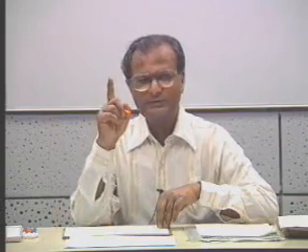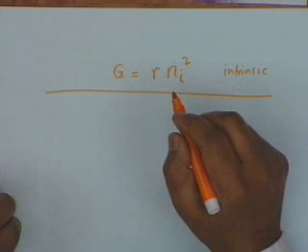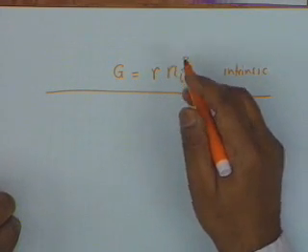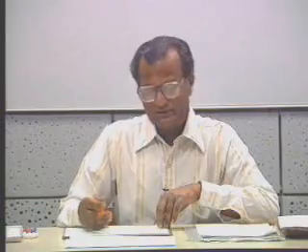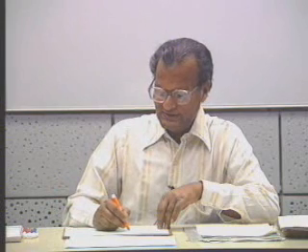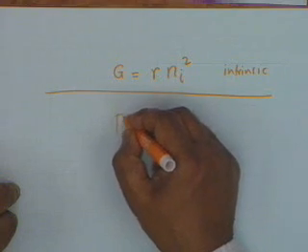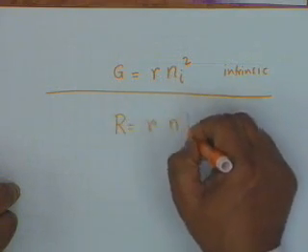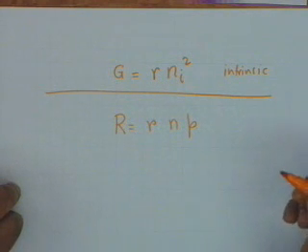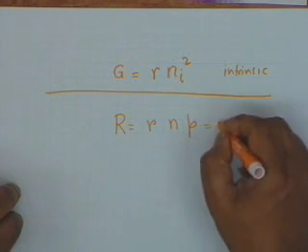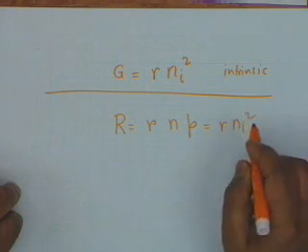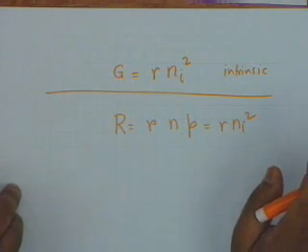There may be one hole generated per 10 to the 7 silicon atoms, and therefore the rate of generation basically depends on temperature, which means that under any condition of doping, the rate of generation remains the same, which means that the rate of recombination, which is equal to R times N times P under thermal equilibrium, should be equal to R Ni squared under any condition of doping.